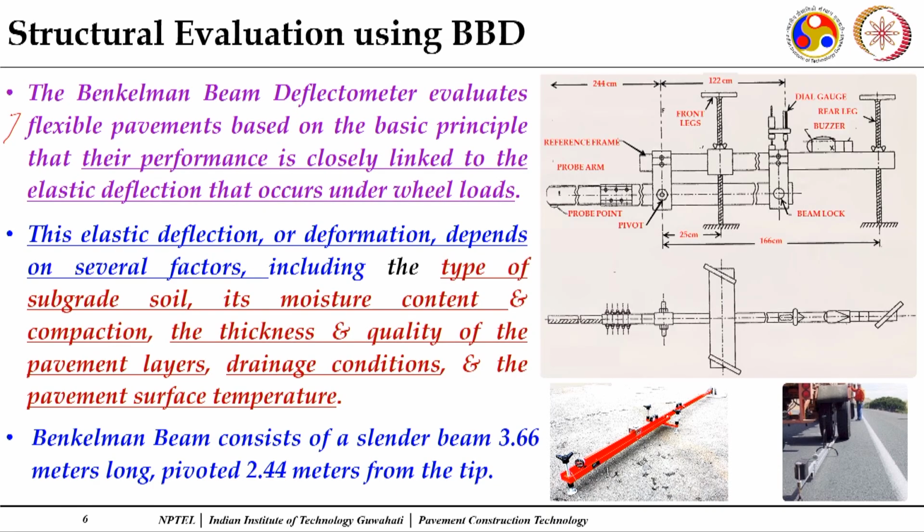What is required in a Benkelman beam deflection study is, first of all, the Benkelman beam. It evaluates flexible pavements based on the principle that their performance is closely related to the elastic deformation that can occur under wheel loads. Here we will use static loads and look into the rebound deflections which take place.